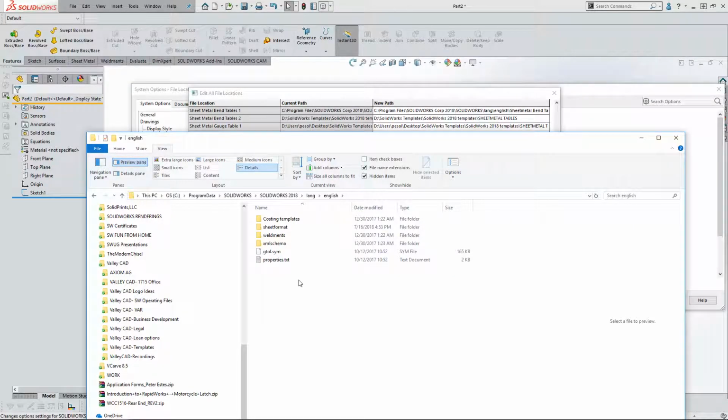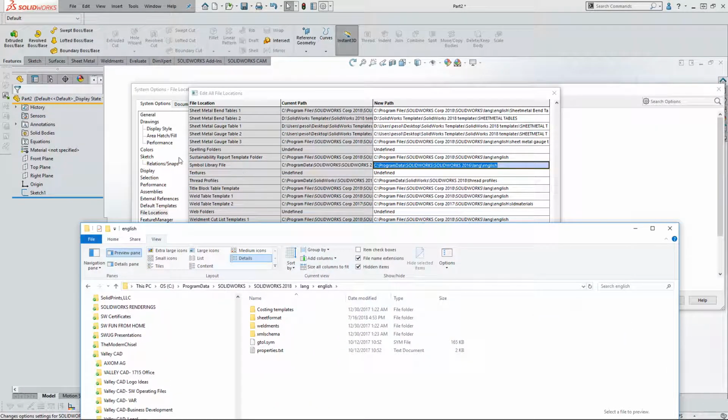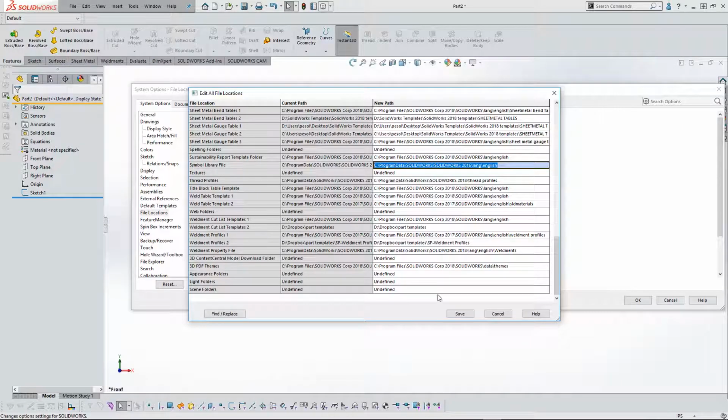I'm happy to email you the gtol.sym file. Or if you have other installations of SOLIDWORKS, fellow coworkers whose installation worked just fine, you can tap them on the shoulder and say, hey, can I get that gtol file from you? And then you could show them this video and say, hey, look in this location. What we want to do is make sure that our SOLIDWORKS 2018 installation is not looking to this 2016 location. We can go ahead and minimize this for a minute.